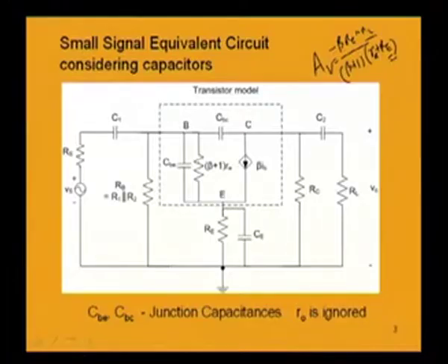Now the current coming into the base point, without these two capacitances, would have flowed through this resistance beta plus 1 Re, but now a part of the current is being shunted away by this CBC and CBE, because their capacitive reactances are now low. Earlier it was almost like an open circuit, very high, in the order of mega ohms. So it was not possible for current to flow through them, but now a part of the base current will be shunted away by these two capacitances, because they are offering lesser and lesser reactance.